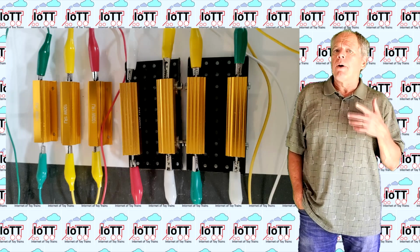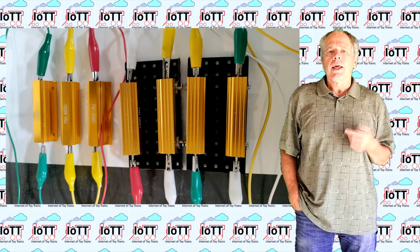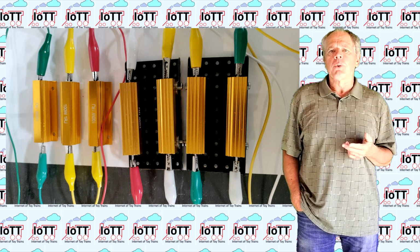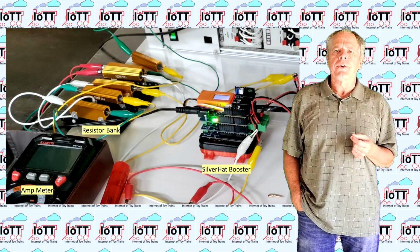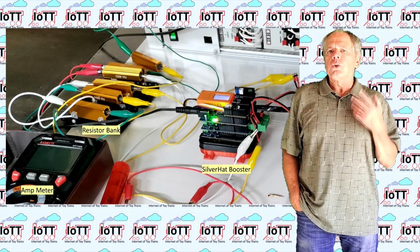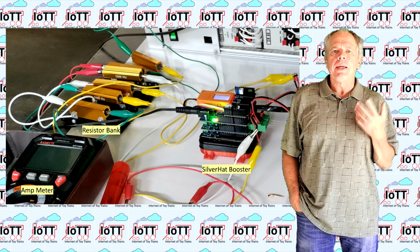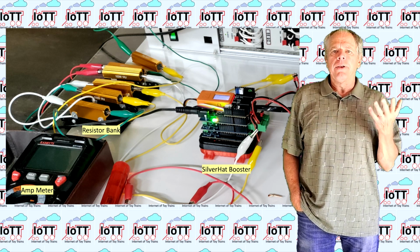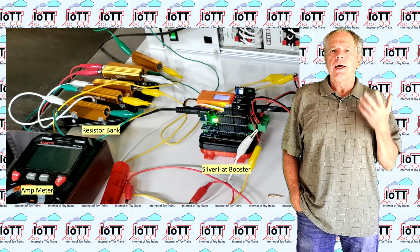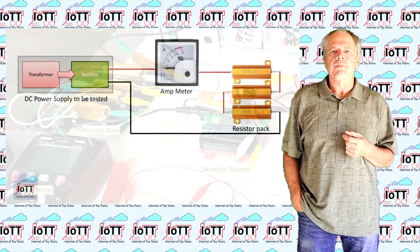So I set up a bunch of power resistors to simulate the regular track load and added a silverhead booster to measure the short circuit current. The silverhead has a built-in function to do exactly that, and it returns the short circuit current in milliamps at about 1, 50, 100 and 140 milliseconds after triggering a short circuit.